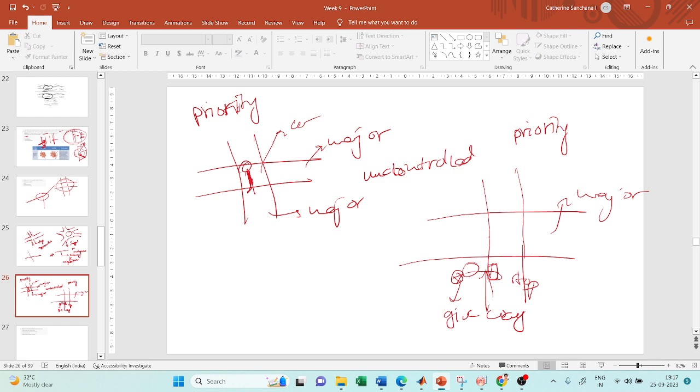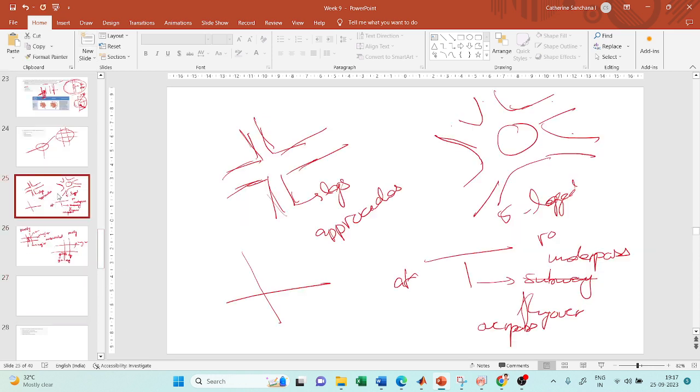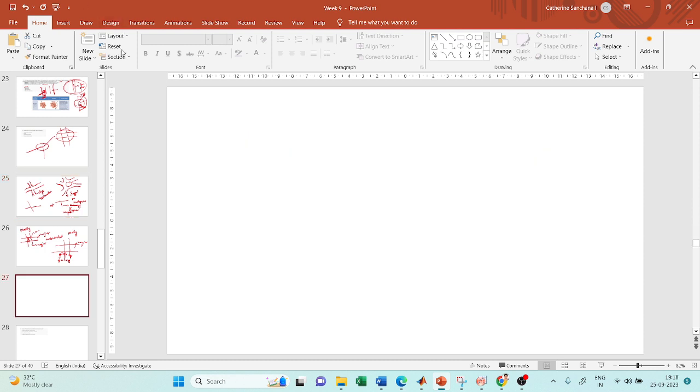So based on the level of control that you provide for the different roads on the intersection, it can be called a controlled or signalized intersection, an uncontrolled intersection, or a priority controlled intersection. Okay, now by combining these two. First we saw grade separated intersection, right? That is a space separated intersection. So these two roadways which are crossing each other are separated by space.